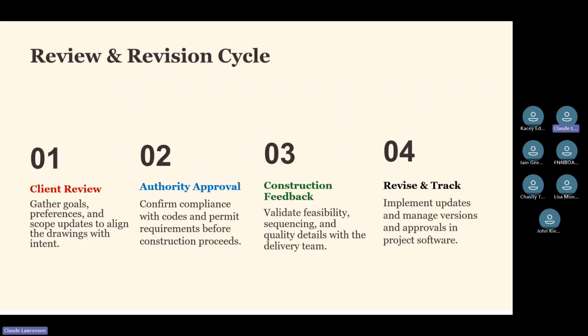It also, for example, one thing I didn't really touch on is it also talks about land coverage. What percentage of land can be covered by that particular building? Certainly secondary buildings such as a shed or we'll call it a patio, those are okay. But the actual main building itself had to be within a certain percentage of maximum limit of coverage on that particular lot.